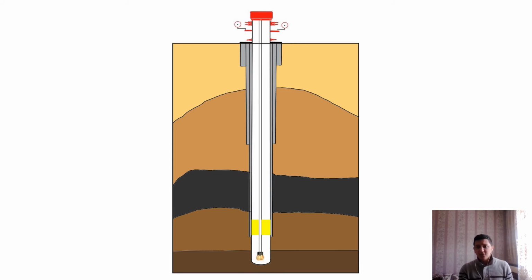In driller's method, first the influx is removed by pumping original mud. At the same time, kill mud is prepared. Once the influx is out, the well is shut in. In the second circulation, kill mud is pumped and the old mud is being displaced. Driller's method is taking longer, but it is safer than wait and weight method.